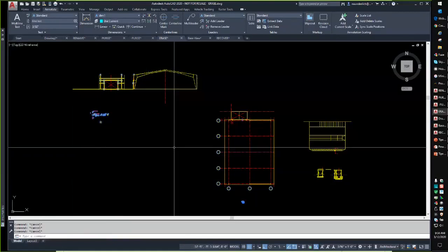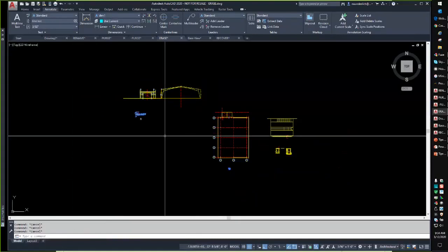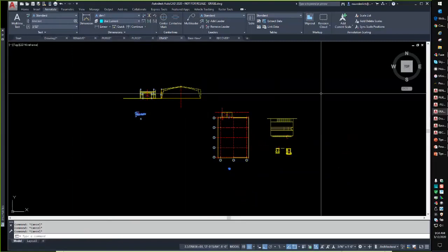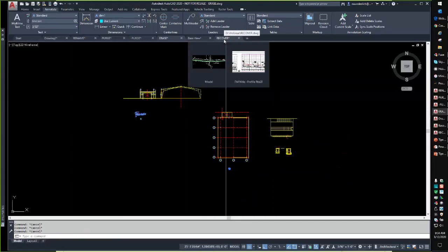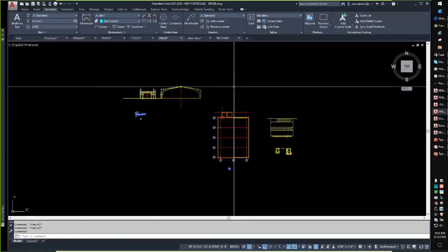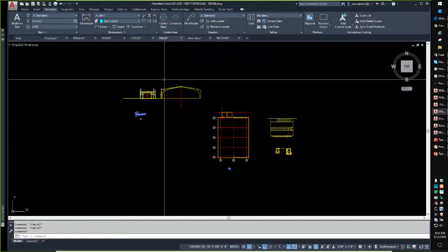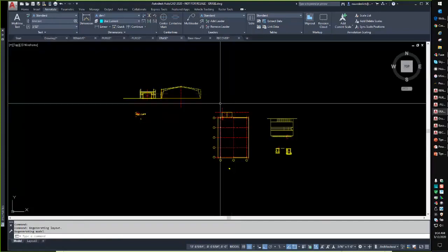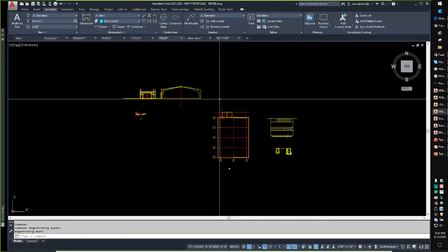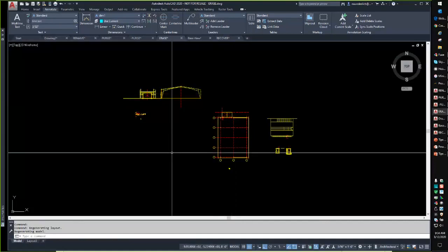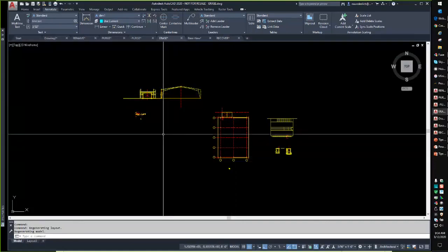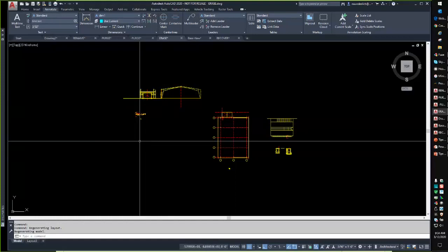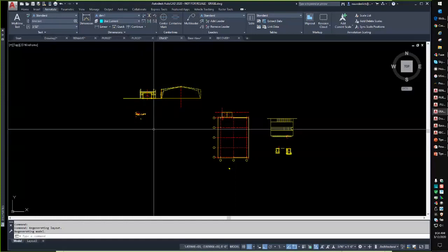So generally speaking, that's everything that I go through in a drawing cleanup process. What I usually look for is if you contact us and you're saying you're having trouble with the drawing, those are the typical things that I go through on a regular basis, where I do a recover first and look to see if anything comes in the salvage database. Then I may come through and just do a minus purge reg apps. I may do an erase all to confirm that you don't have any extra garbage in that drawing that's come in. I know that in the past I have seen people insert blocks that all it has is layers and line types. That's not a selectable drawing. But the problem is once you've inserted that drawing, you cannot get rid of those layers until you purge that block definition entirely out of the drawing. And if you can't select it, you can't grab it, you can't pick it, you can't do anything. That's when the erase all comes into play.